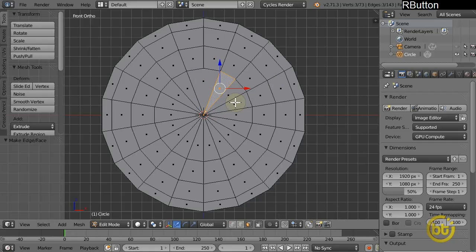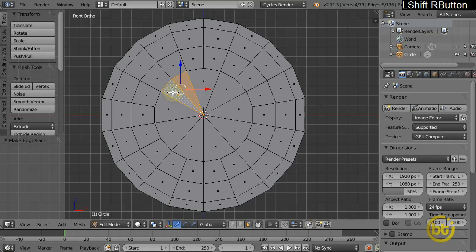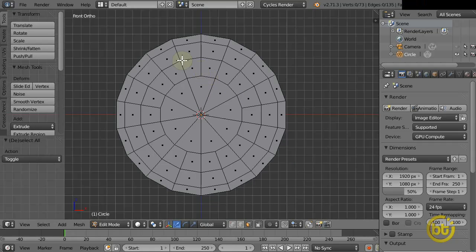Okay, now go to the face selection mode, select these two faces and join those together. Why I am doing this is that here we're going to convert this triangle into quads, and do the same for the rest of these faces like this. Select these two, fill this one, select these two, F, select these two, F, select these two, F. Okay, now this one is done.